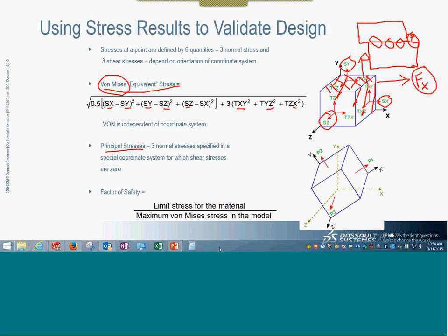And when we are creating elements, we are actually approximating the geometry. Plus, these matrices are going into a particular solver, and it is basically a matrix which is getting solved. So when the number of elements keeps increasing, from a mathematics perspective, we are actually reducing the accuracy. The accuracy goes lower and lower and lower. And I'm talking about millions here. It is not about thousands.